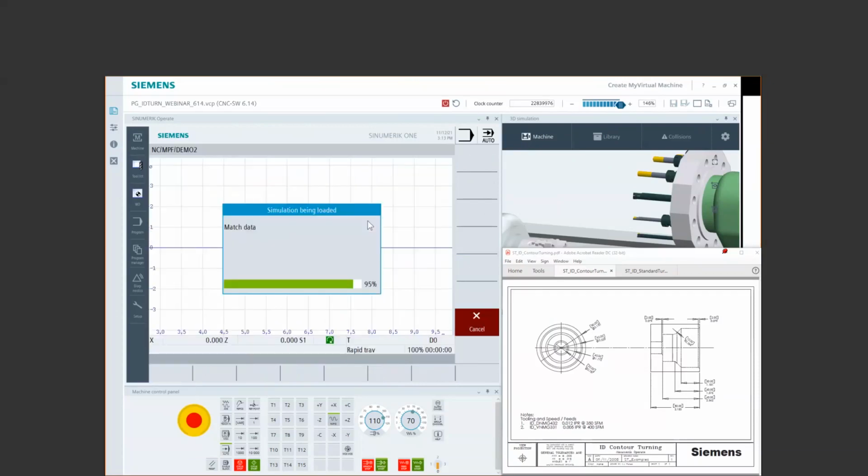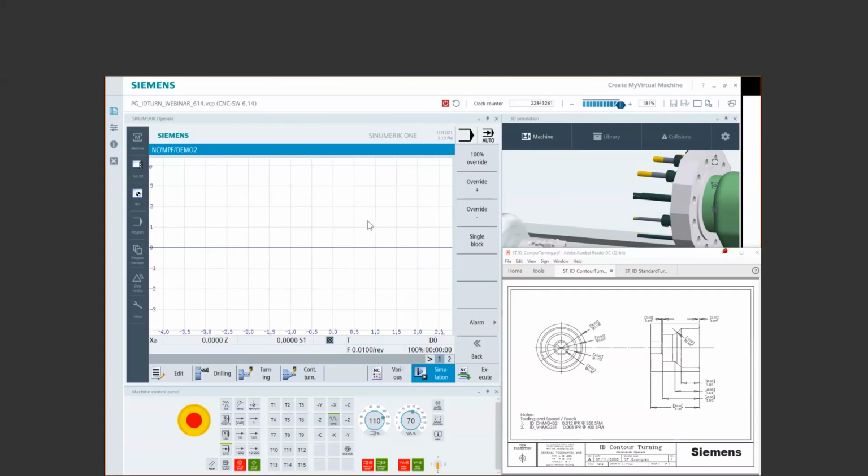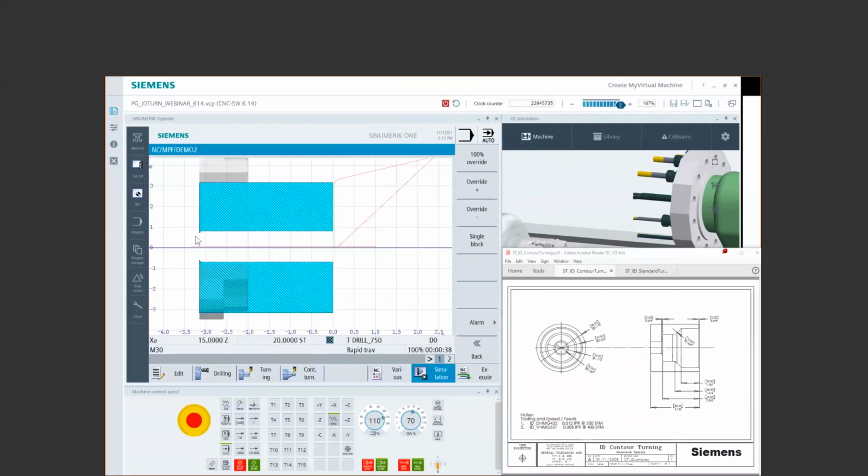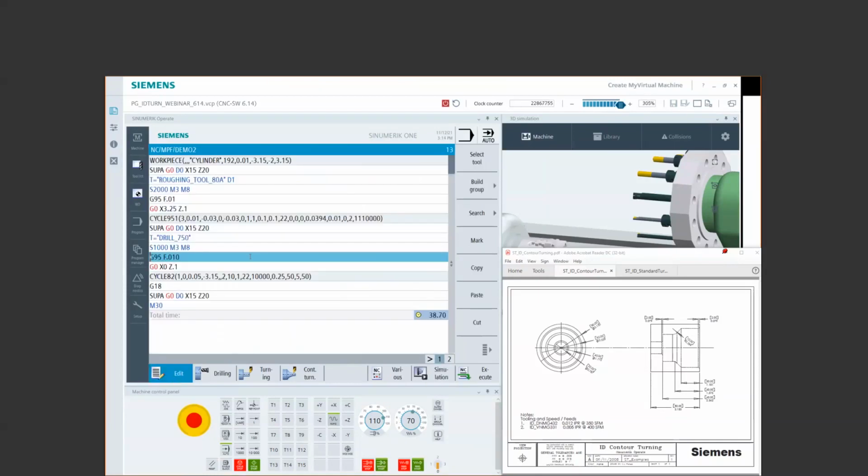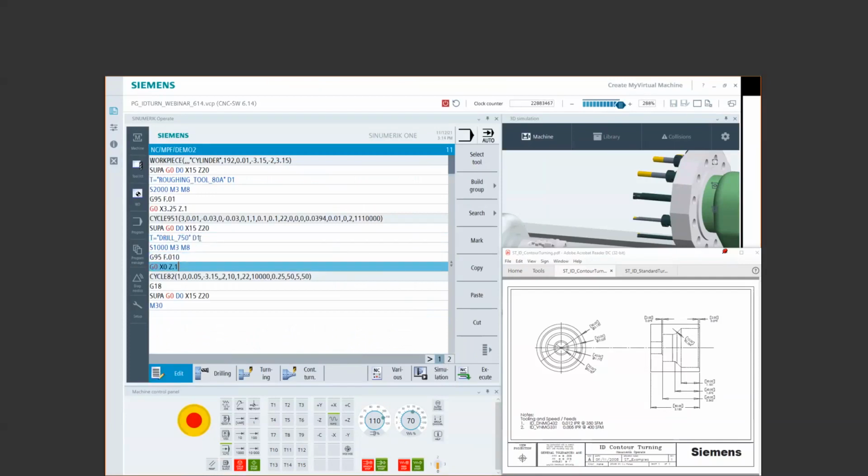So in this case, remember I'm programming based on the shank of the drill. So there you see it pokes through. Had I not done shank, then I would see the full tip here because then I would be only going that 3.150 to the tip of the drill. Had I forgotten to preposition, or prepositioned it somewhere else, it would have tried to drill this hole off center and graphics wouldn't have known that this machine's not capable of that. So that is on you. You have to know enough to say, is this a live tool or is this a static tool? If it's a static tool, make sure you get her to 0. That's important.